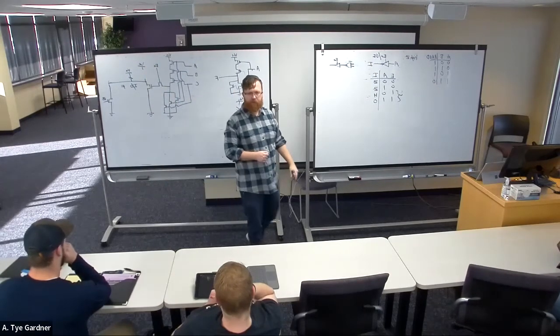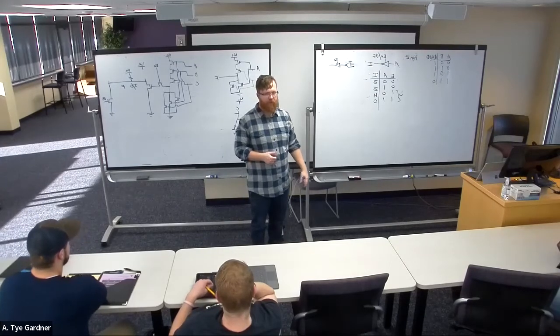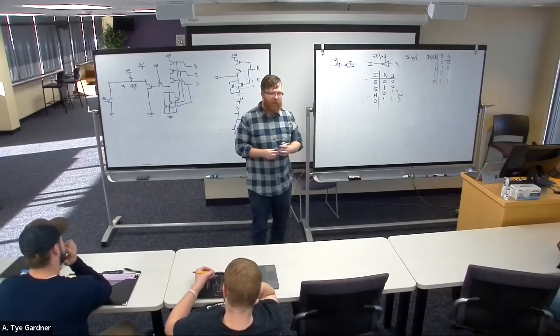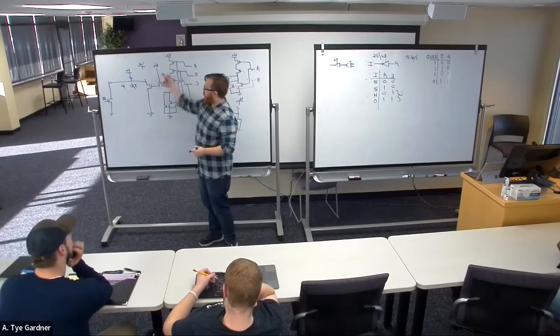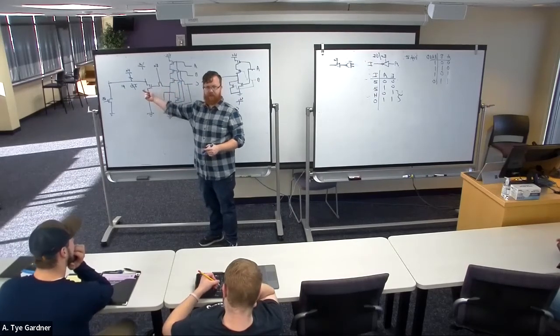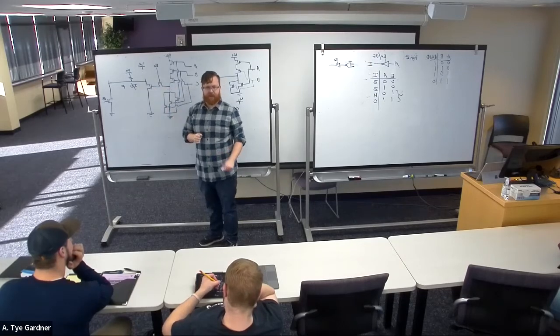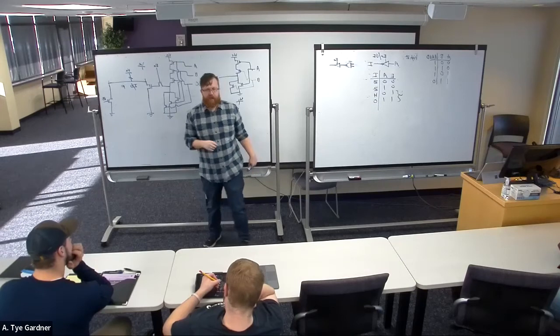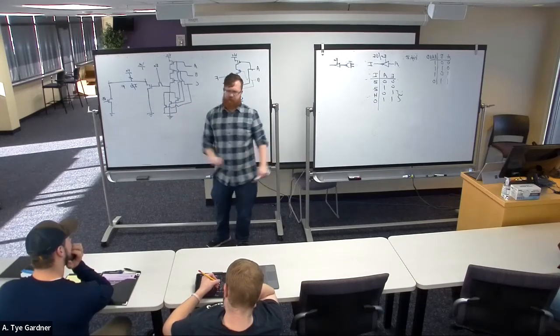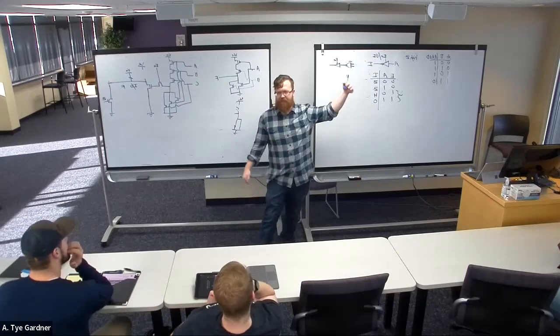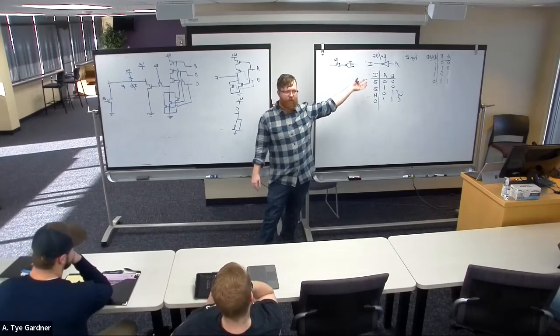Ta-da. They can function this way. They're pretty good at it. Where if enable comes in and turns this device on, it flows through. If enable is 0, then they're broken and it can't transmit anything. Now I've actually added that signal in there explicitly. I don't think you need to worry about drawing these ever, but that's all this signal is saying, that I've added a signal that allows it to turn on or not.